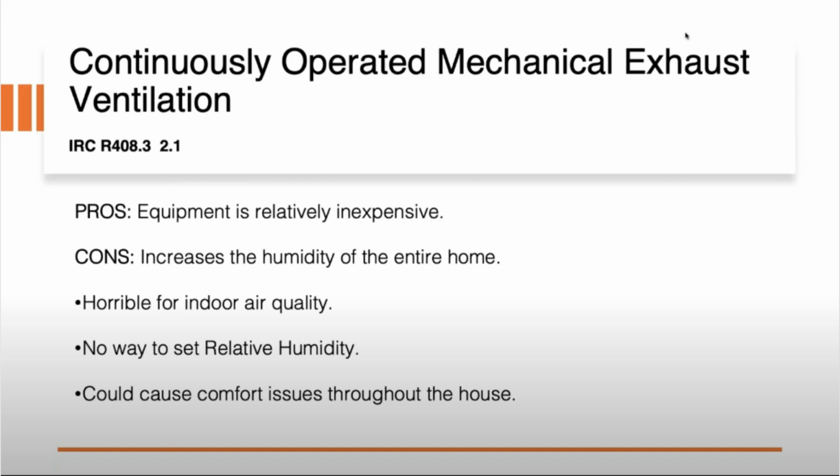Then, we commonly see other contractors come in and try to sell a conditioned crawl space cheap and cut all the corners to do it at a low price. This leads to situations where the moisture never really gets controlled. Once the crawl space has been conditioned correctly, the air infiltration issues and bulk water issues have been solved. All we need to worry about is relative humidity. What I am alluding to here is the fact that conditioning really means moisture control.